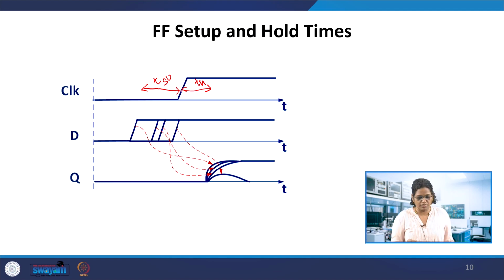In the case of flip flops, the setup time extends up to the active edge of the clock, whereas for latches it extends to the inactive edge, as we have seen in the previous diagram. Here, suppose the data is changing exactly at the clock edge. Then the impact is that the output shown over here won't be reflected properly, it won't go from low to high.